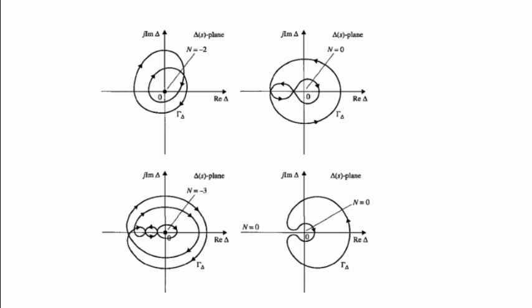Now let us consider these various closed loop contours. Here is the origin, and we draw a straight line from the origin towards the outer region of this closed loop contour. Here it is cutting 2 times, so the number of encirclements about the origin in the delta of S plane is -2, because conventionally we say that there should be counterclockwise encirclement.